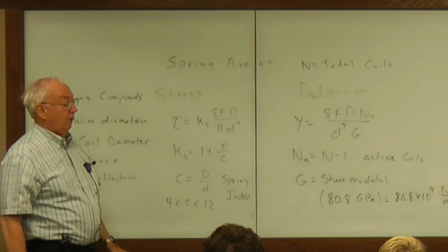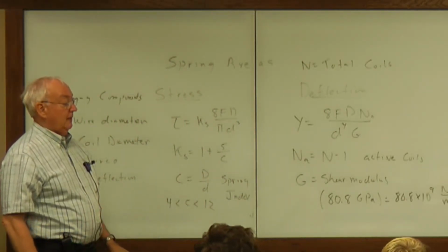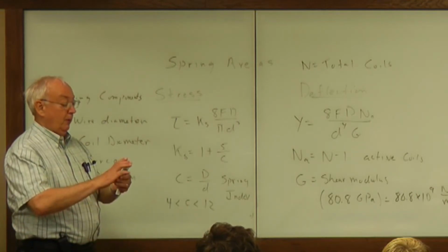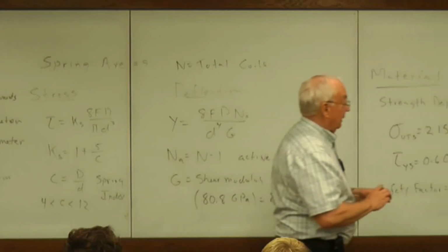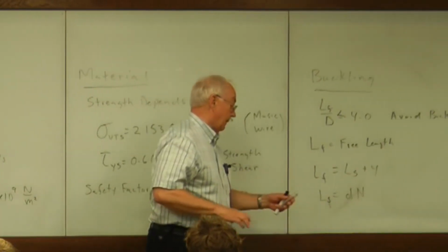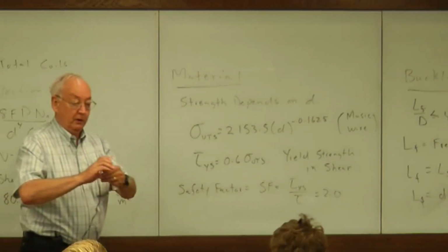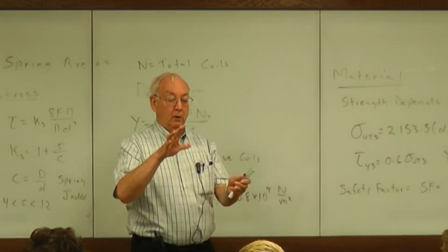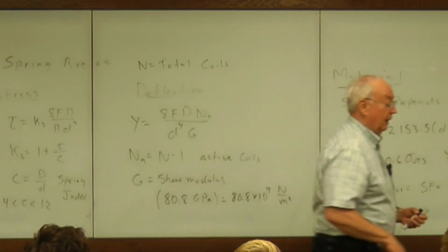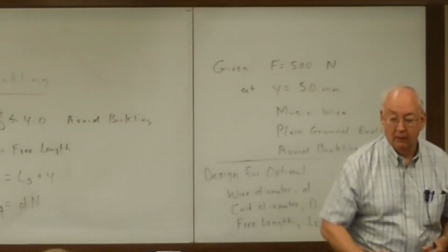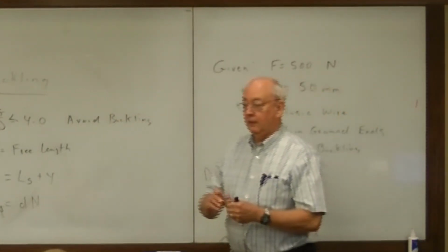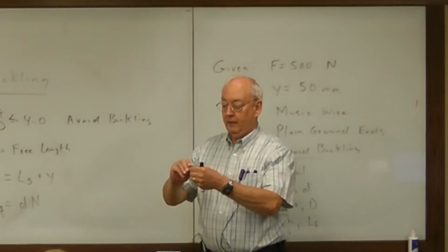And rather than design to that, a lot of springs design so that when you get the shut length, which is when you compress it all the way down to where all the coils touch each other... Most of these springs I can't compress to the shut length. I don't know if any of you are bodybuilders, but I can't.